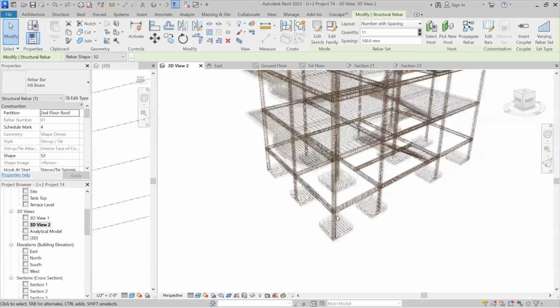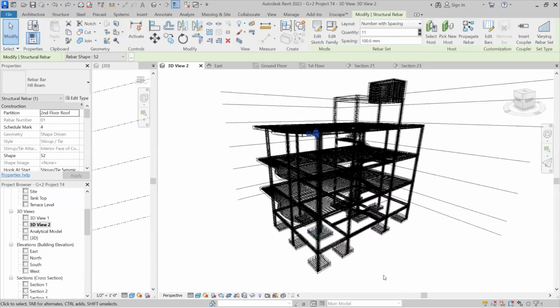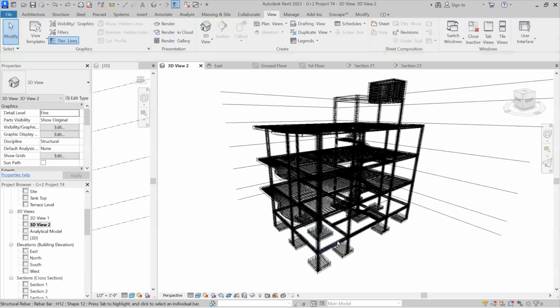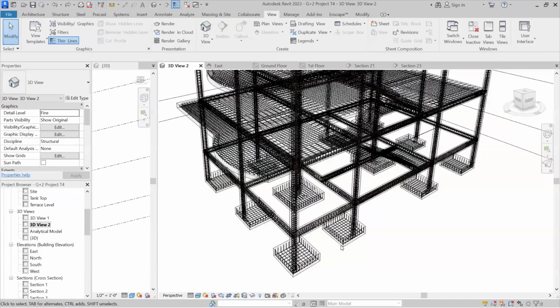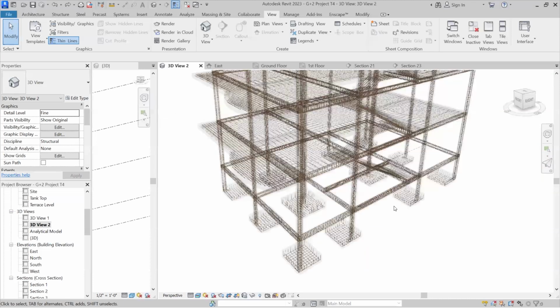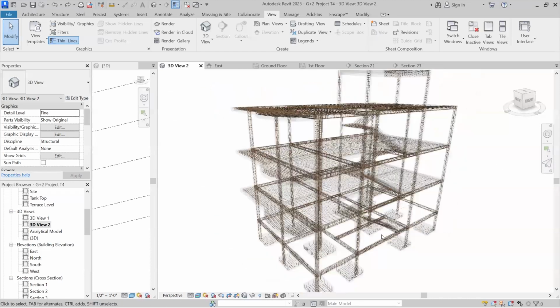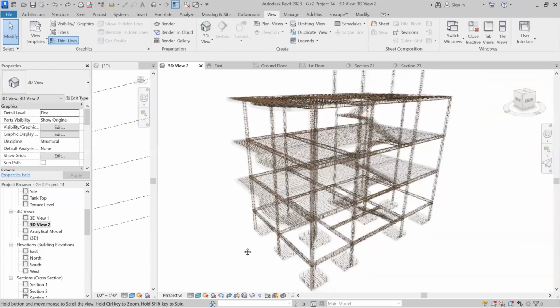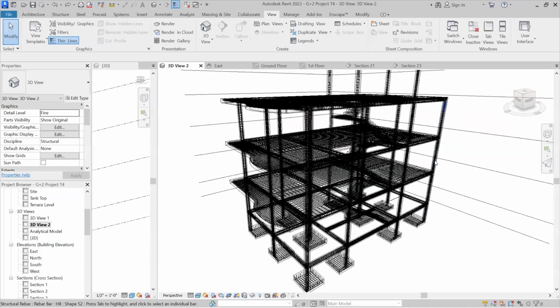3D. For learning purpose, first you have to learn how to place rebars, so you should place every rebar by hand. After that, I have taught about plugins that you can use to quickly place rebars in this entire column.